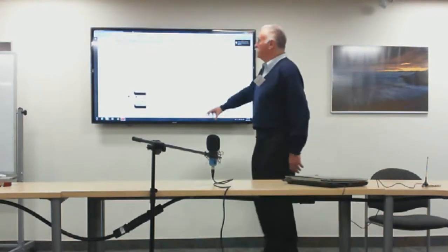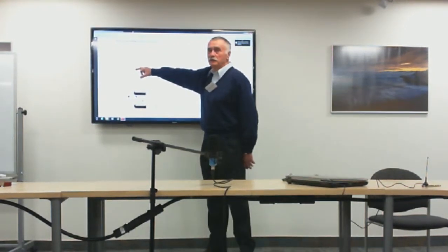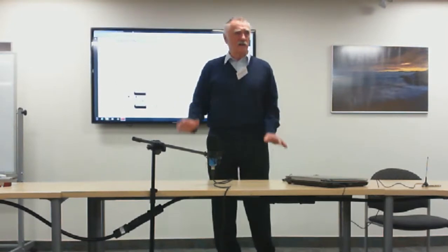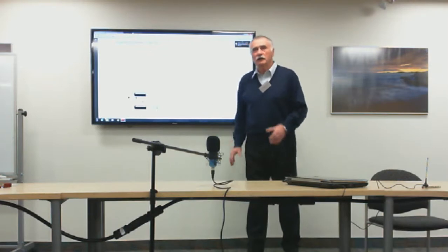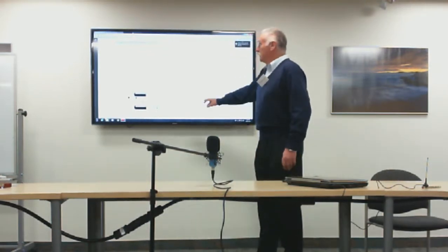So this switching can be done down in the transceiver or right up on the antenna if you have separate transmitters and separate receivers. Both cases are widely used in ham radio. Lots of home brewing on the VHF, UHF, and microwave bands uses the format of a separate transmitter and a separate receiver, and the antenna relays are up on the mast.